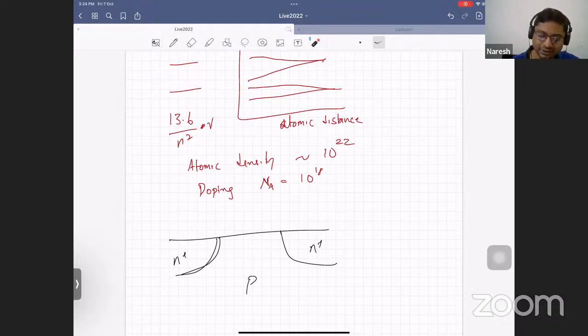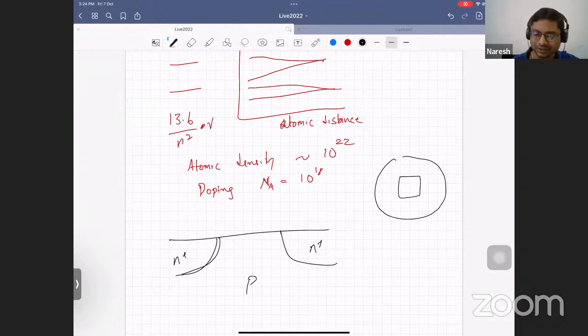What we do is, let's say you take a silicon wafer like this. Let's say you want to dope this area with N plus, and this is a P-type substrate. I want to make it N plus here. This is the top view. If I want to do this, I'll take, let's say, arsenic and accelerate those arsenic atoms, and they become ions, and those ions impinge on this from the top like this.